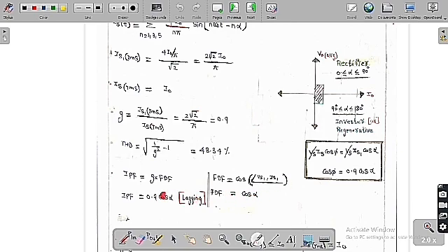So you can multiply these two things. We get input power factor equal to 0.9 cos alpha, because it is lagging, as we are using inductors. It will always be lagging, meaning the source current lags the source voltage. So input power factor is equal to 0.9 cos alpha.